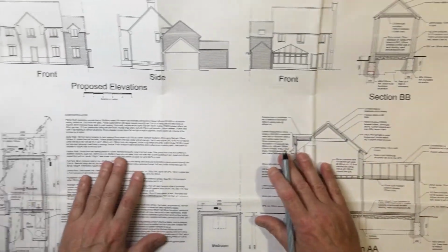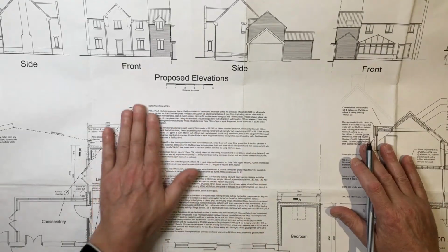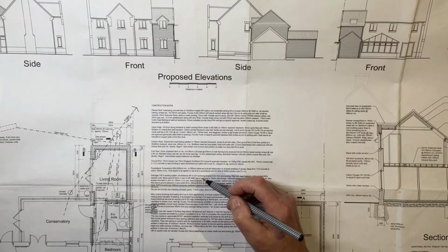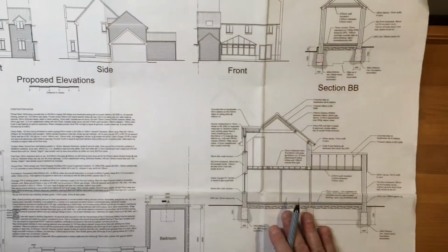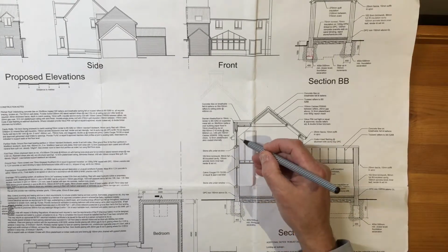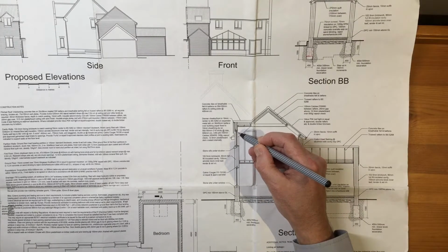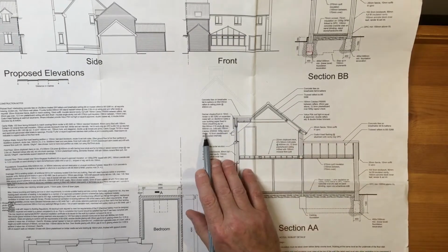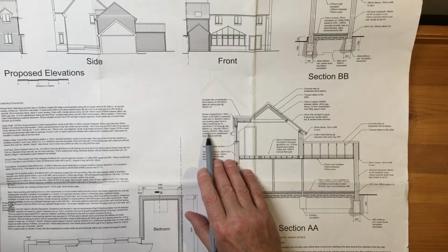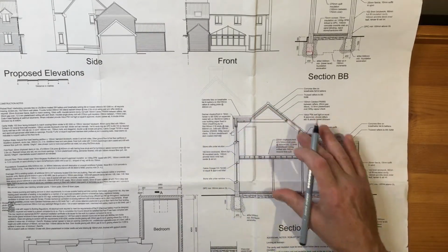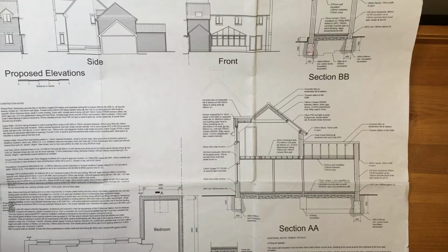And he'll also look at the construction notes, the specification they call it, to find out any fine detail, such as the type of timber used, type of insulation, the type of bricks, even the type of lintels used above the openings in the wall for the windows. It's all very important to get it right. And you can see there's some actual specifics even written in here, specifying the exact detail for this particular job, and they will vary. So let's look at this drawing.